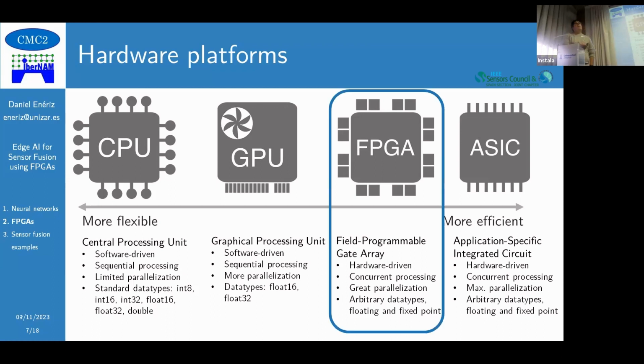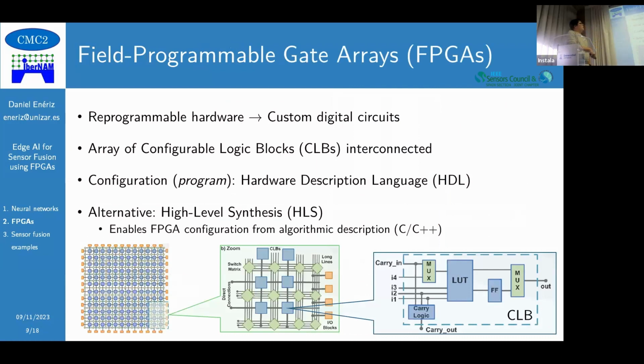And for these reasons, we believe that the FPGAs are well suited for implementations that also require power efficiency, real-time responsiveness, or even ultra low latencies. So since they are not pretty common, I want to introduce them a little bit. Basically, they are reprogrammable hardware, meaning that you can build custom digital circuits inside of them.